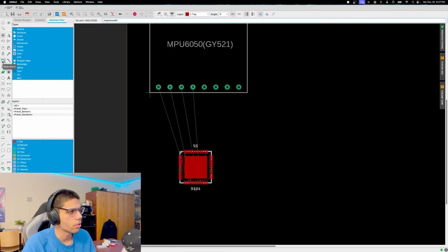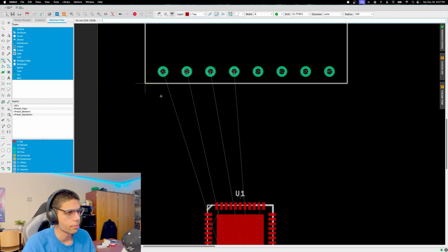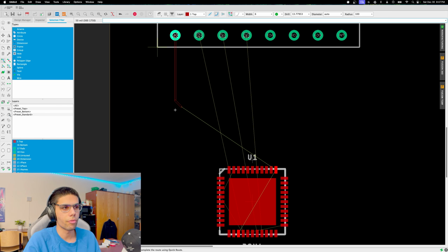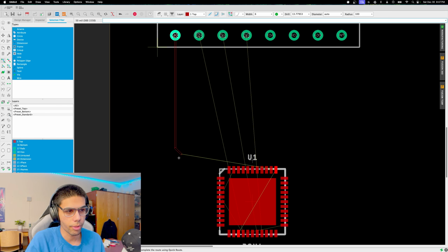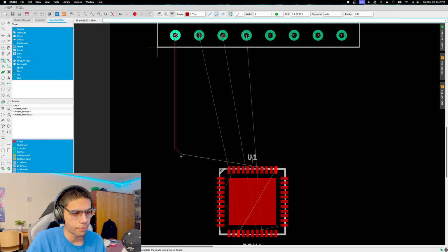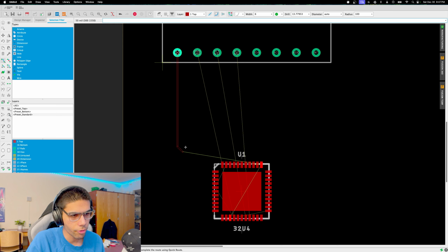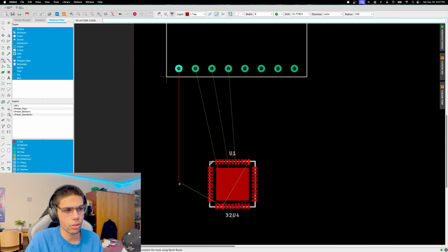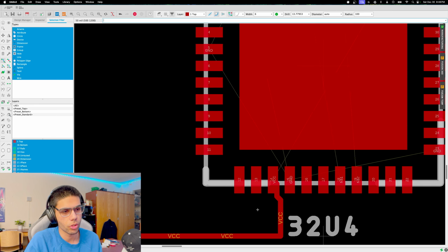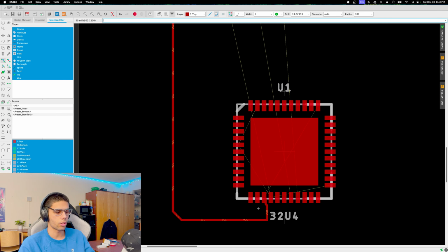You're going to click on this route a wire tool, and you're going to click on a pad. So you will be able to see a wire, a copper path, coming from that pad. So there are 4 ground connections on this chip. So you can use any of the grounds. You can use this ground. So this is one of our many connections.